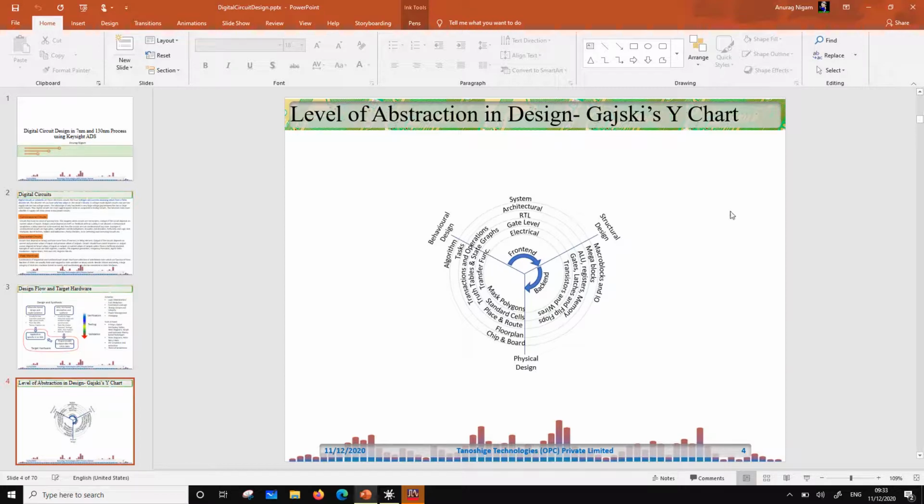In behavioral design, we can start with the transfer function, we can have truth tables and state graphs, we can have transitions and operations between states, right? And then we can design tasks, and then using various tasks we can design algorithms, and this description basically is automated to generate the circuits, and this is usually the route taken by what is called high level synthesis. At the high level we can just specify the algorithms and translate that into a digital circuit. So that will be a behavioral level description, right?